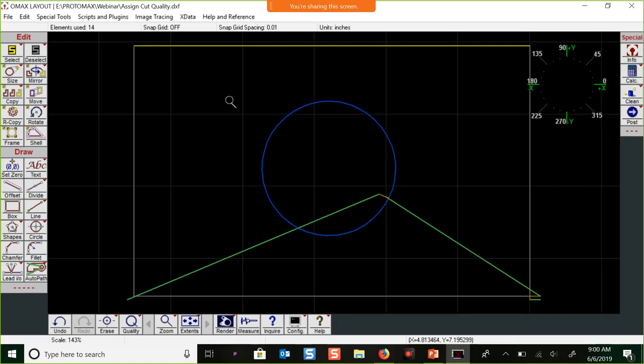Now, if you don't want to muck around with anything and you're okay with an etch quality of 100, then that's your predetermined speed. The thickness of the material would determine how much speed you're going to need. The best way to determine this before you start cutting on the actual material is to get a similar scrap piece and test your etch quality there before you waste your good piece. So etching is definitely one of those things that you're going to have to play around with. It isn't just hit a button and go. You're going to need to spend some time with it.